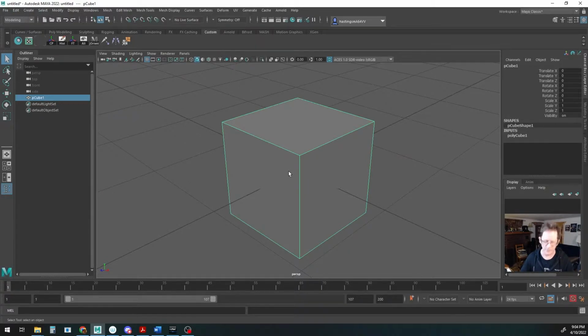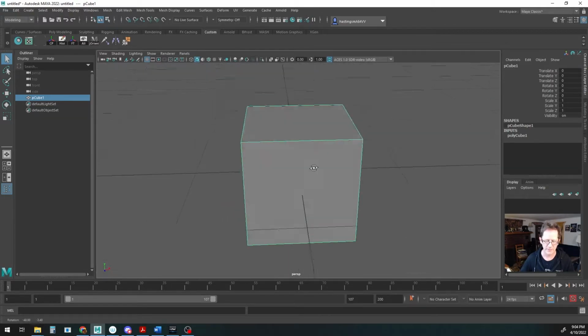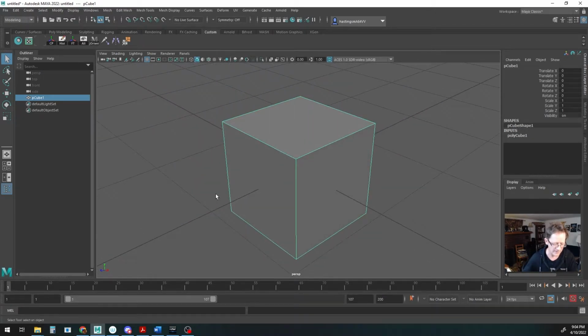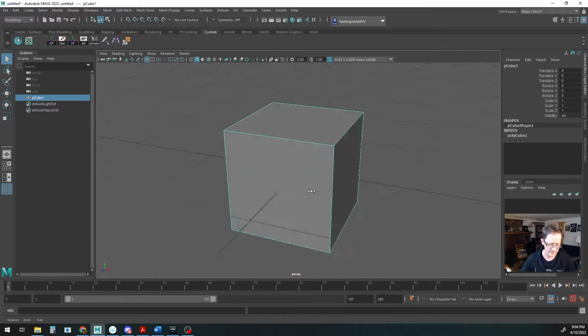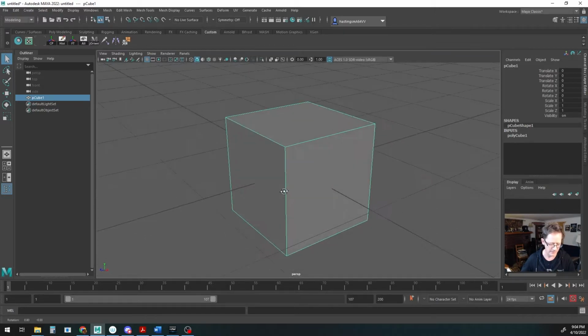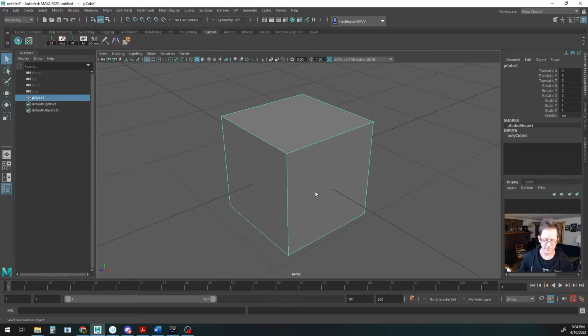Now, to move around the screen, everything you do, you always hold the Alt key down. So you hold the Alt key down, and to rotate, you hold the left mouse button. So Alt, left mouse button, and you can rotate this object in all these different degrees. If you look down here, you can see the coordinate system. We have Z coming over here, X going over there, Y going up. So I'm rotating around Y there, and sort of rotating around Z. That old gimbal lock is going to really give you some issues. But anyways, enough about gimbal.